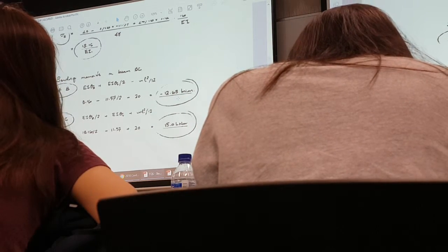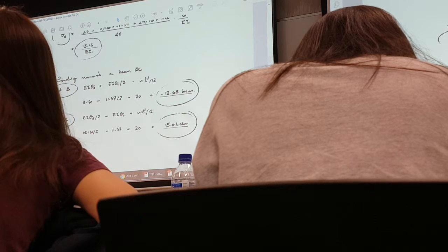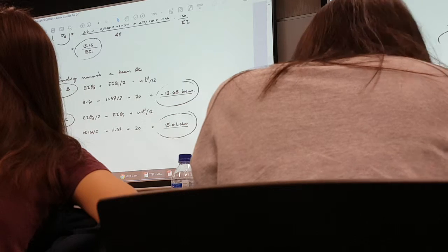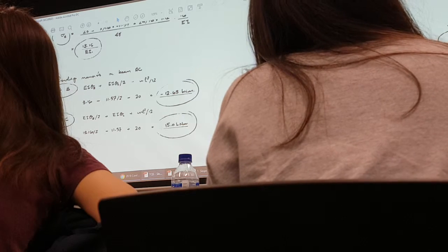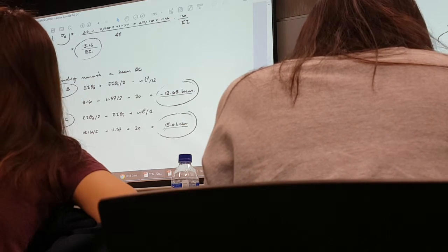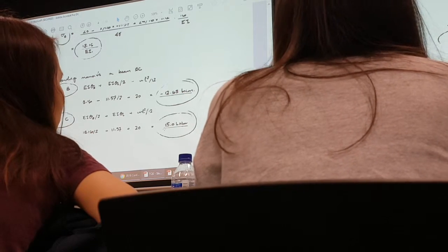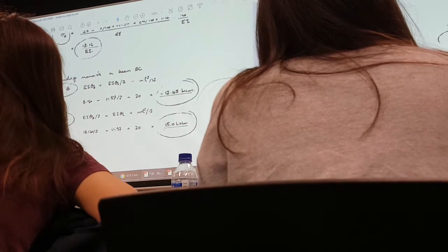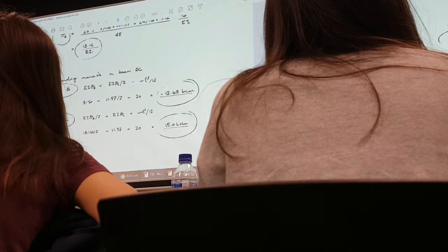And how about the moment at C? The moment at C again is this expression, and now you have to add on the FEM that is being induced, and for this case it's plus 20. So with that, you work it out to be 15.0 kilonewton meter. Right, so that matches well with what the question is asking, to show that the moments at B and C are minus 12.6 kilonewton meter and positive 15.0 kilonewton meter respectively.